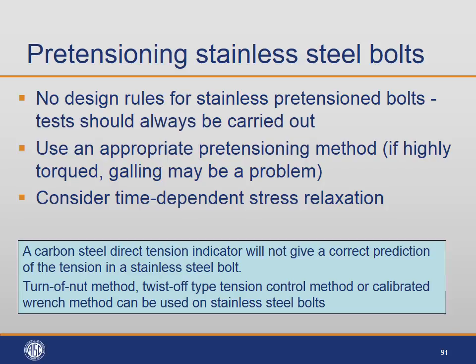And so if you're not wanting to undo the bolts, it's fine, no problem. But if you are wanting to undo the bolts, then it can be an issue. So the design guide gives a few ways of how you can avoid galling. One of the ways is to lubricate the internal or external threads. Another way is to make sure that the threads are as smooth as possible, or to use different stainless steel types with different hardness levels for the bolt and the nut.